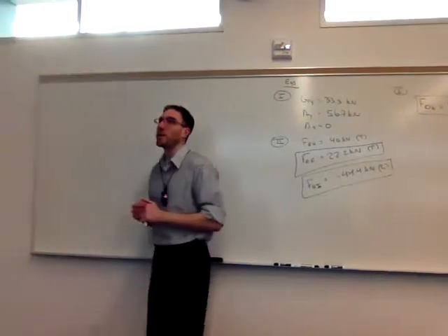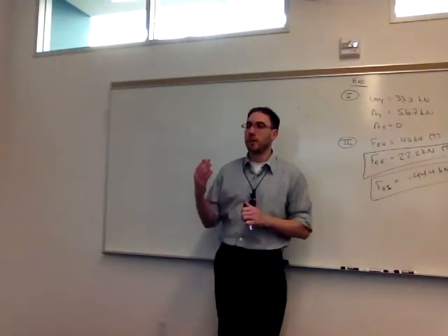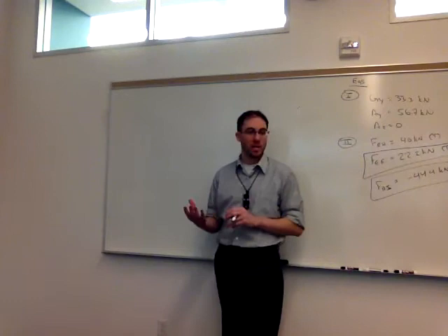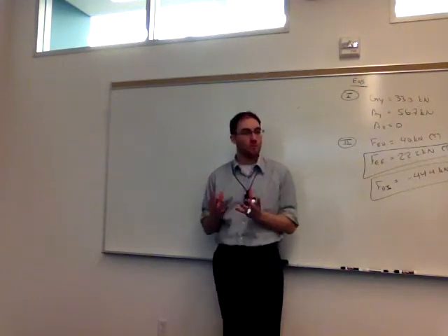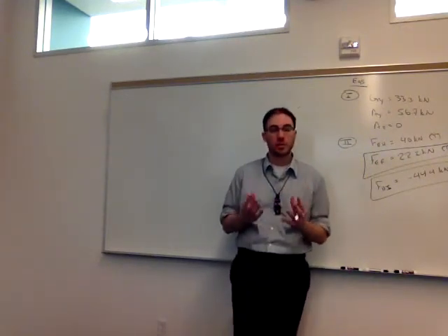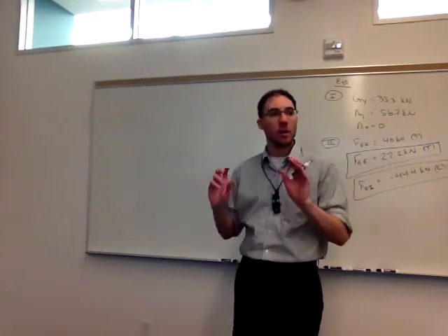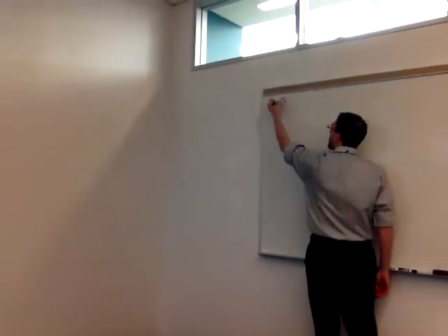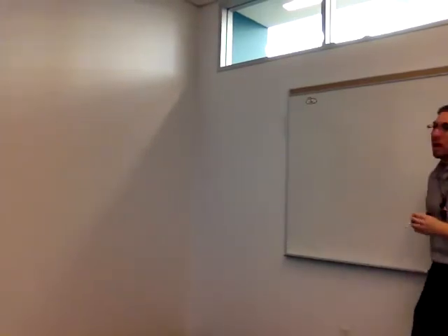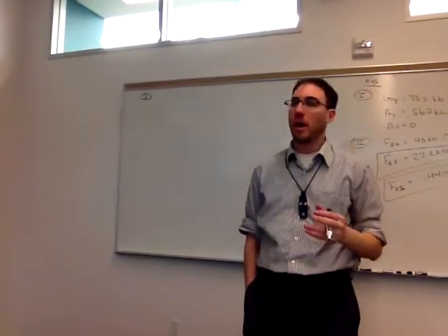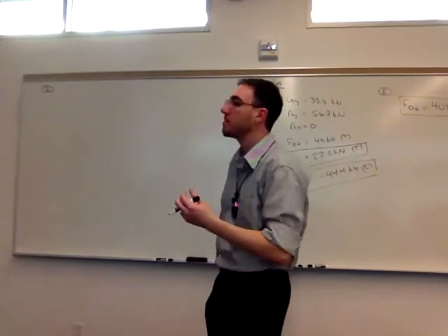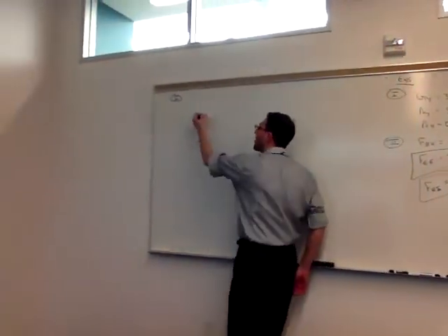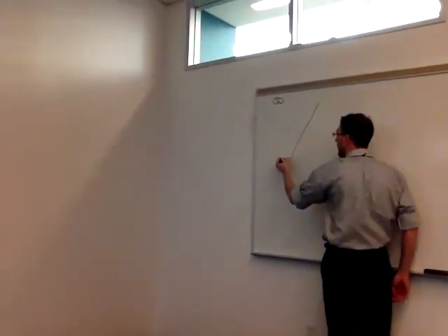Right? So we're trying to find ultimately the reactions at E and the reactions at A. So again, there's going to be 4 external reactions, so it's statically indeterminate. We need to go down to the component level to do the analysis. So it doesn't matter where we start. So I'll just start alphabetically for that reason only. So I'll draw member ABC first.